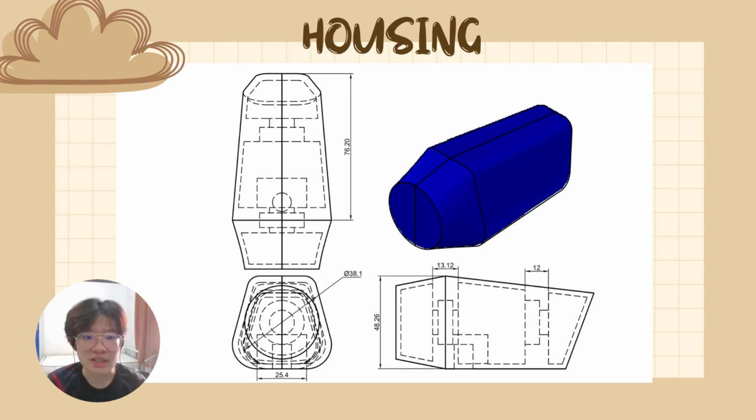When two planes are connected, all the solid structure was mirrored to form the complete structure, because the plane that we had drawn is a half plane. Union command is used to combine all the solid structure into one. Next, a reference line is drawn in the inner part of the housing structure, with a depth of the fundamental shell using the offset tool.